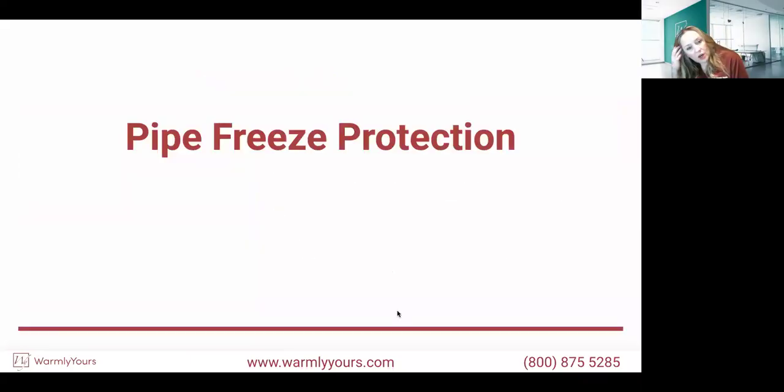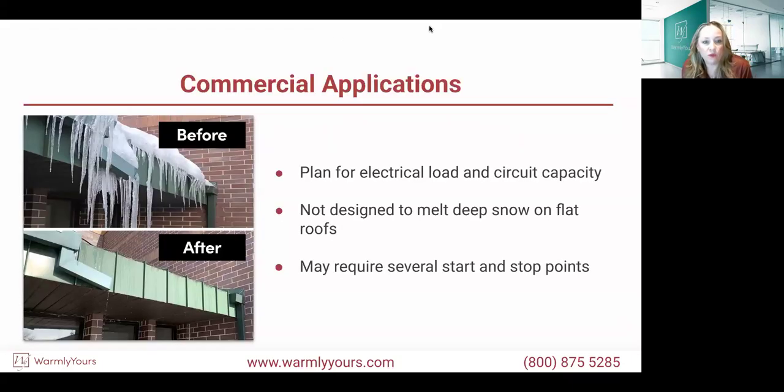And I see a question just came in from Ryan, asking about metal roofs: do I have to use self-regulating cable? Yes, right? We're not using the constant wattage on anything, correct? Yeah, much like the asphalt roof, for metal roofs the constant wattage product is not really made for that application. So yes, correct.